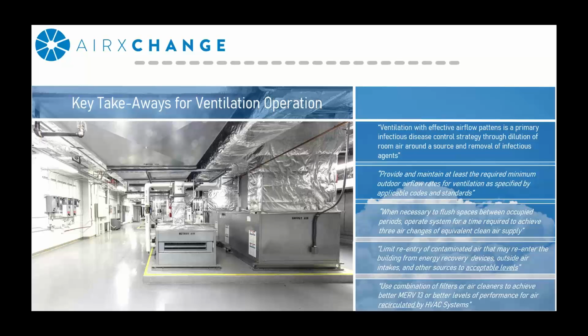You're going to want to provide at least the required minimum outdoor air ventilation rates as specified in ASHRAE 62. Now, for some of the folks, this may be difficult, as units that operate over time have a tendency to get less efficient. This also applies to airflow delivery, and I'll speak in a couple slides on how to maximize that. If you have the ability, flush the space between occupied periods. The current suggested rate is to provide a flush equivalent to 3 air changes.